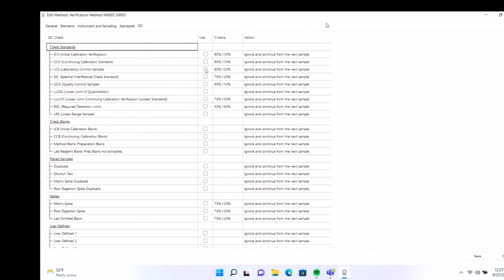Going over the Standards tab, you can add standards, remove standards, put in the concentrations, through origin, if they're weighted or not, the weight of them, the fitting method, your minimum correlation coefficient, and your standard error for the standards. The final tab is the QC tab. Clicking on any one of these puts this into the choice in the session. So back to the sessions, we had the sample types, the standard, sample, and if one of these are chosen, this will be a choice in there too.